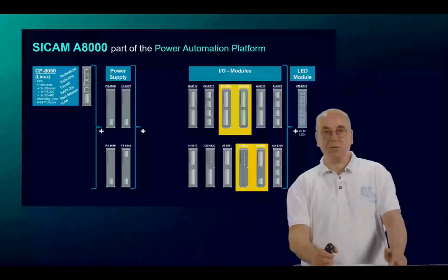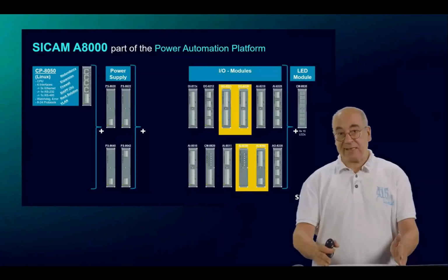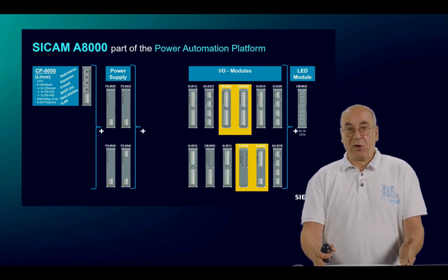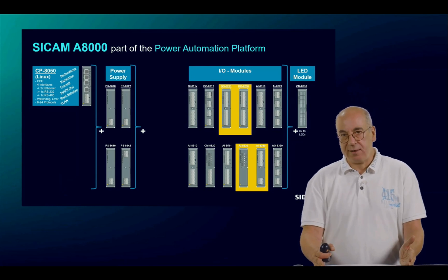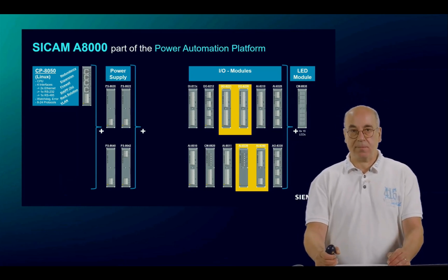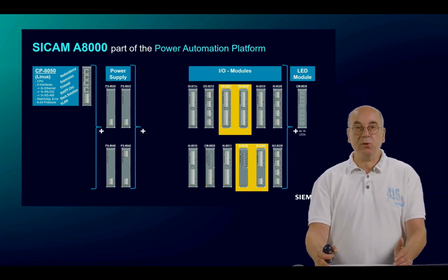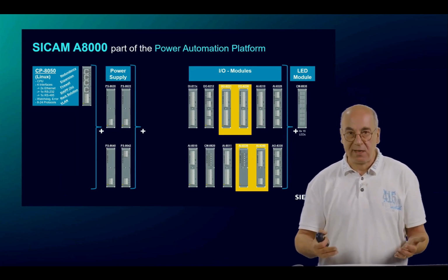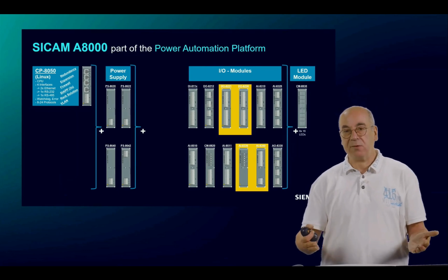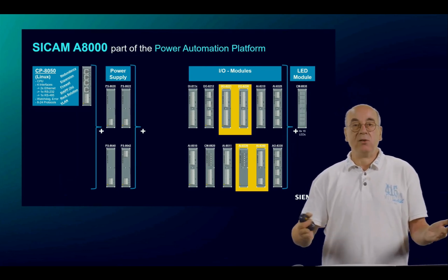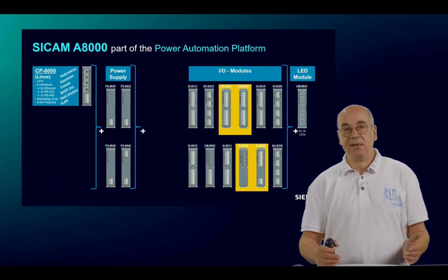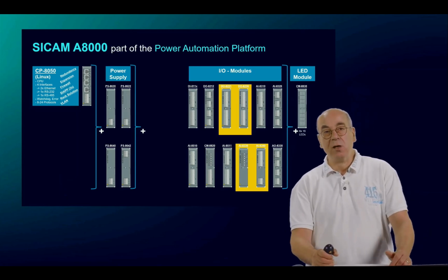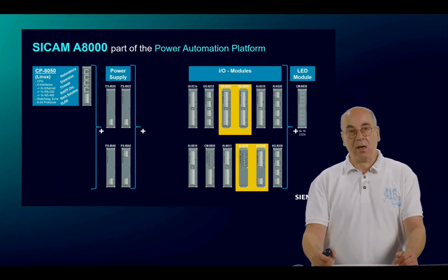And you can separate your network connection by using the application layer firewall functionality. Another way, a separation using virtual LAN technology or functionality, is also possible with the Linux-based RTUs. And additionally, you have the possibility to provide up to 3 protected runtime containers for installing your own application. And we covered this in our CEP webinar, which was also part of this SICAM 8 series. Let us now see what additional benefits and extended possibilities regarding the number of connected input-output modules and the number of physical communication interfaces are possible with our beautiful CP8050.